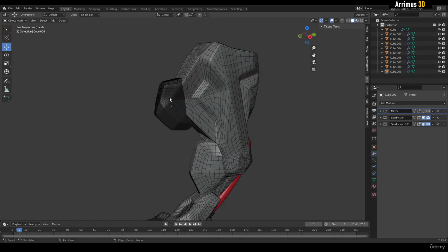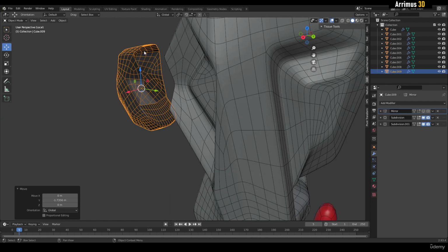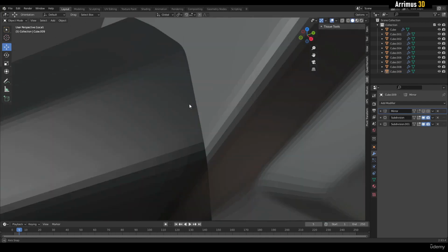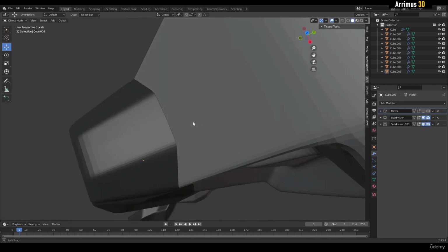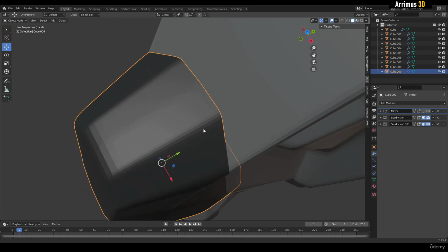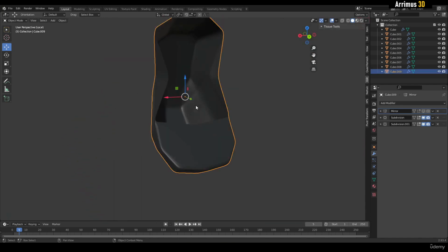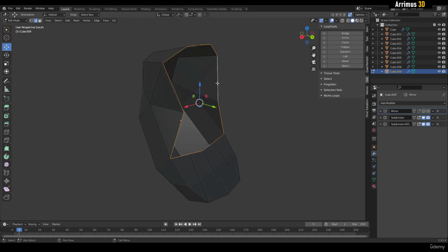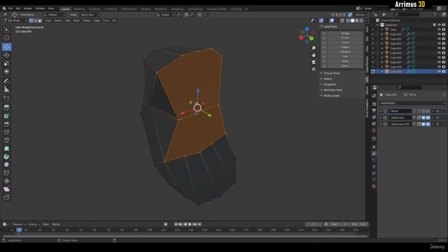And when you simply detach things like this, you get this kind of hole right here, and there's nothing happening here to capture the highlight, which means you just get this awkward transition. So in order to stop that, we're going to Alt and left click, F, and use, perhaps, I like to use knife for this.